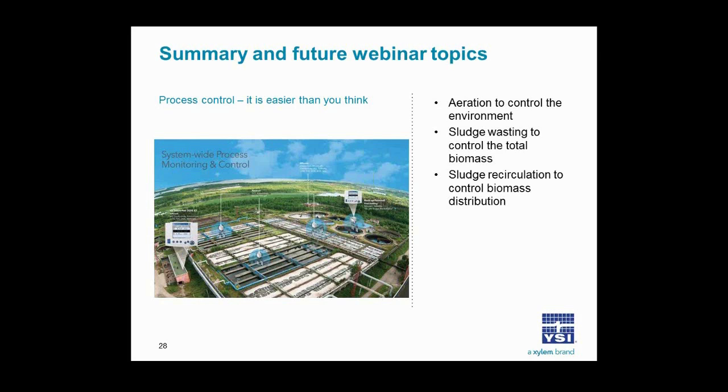We keep high DOs to prevent denitrification from lifting the sludge in our clarifier. What else can be done for this problem? Yeah, I've heard this a lot when I talk about this subject.